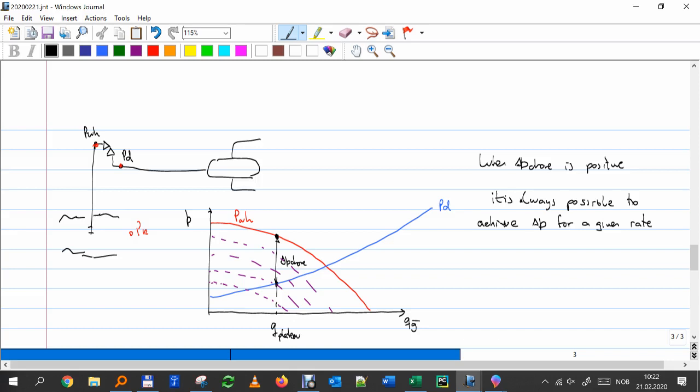What kind of problems might I encounter if the delta P across the choke is too big? The velocities become very high, critical. I have very high velocities in this throat, and I can have erosion. So I will have wear of the chokes very often. That might be a problem.